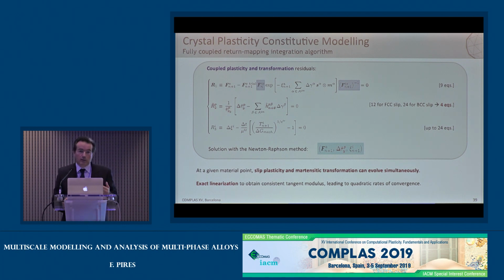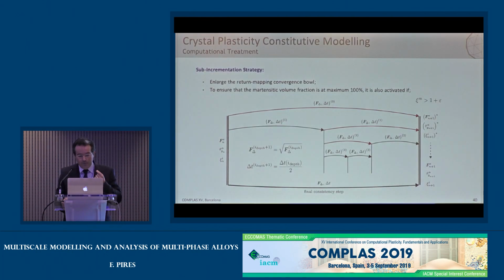And this is particularly important in the context of fully coupled analysis, since we really want to move in time and fast. And if we have an incremental cut at the Gauss point in one RVE, that will force the microstructural boundary value problem to cut, which will then force the macroscopic problem to cut. So after linearizing it and running some problems, we realized that doing the full linearization wasn't enough to run this class of problems. So then we added a few techniques.